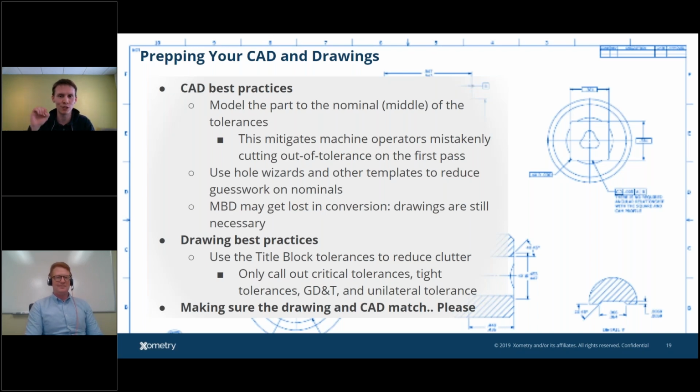It's just click, drag, upload, everything auto-fills there. The other thing is when you are making your drawing, we want to make sure that what we're keeping our eyes on is the most critical dimensions. All processes have general tolerances to them. So if a dimension's plus or minus 5, we can follow the CAD model, and actually mill out that feature and probably stay within spec. If it's critical to function and needs to be measured, definitely show it up there.